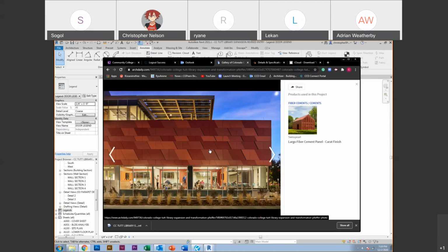You could take an image of this, chop it out, and then make it a material in Revit, and then just spam it that way. It may not always look right just because of how big that image is and where it repeats. It'll be helpful, and it may look right in a lot of instances, but it won't always look right.